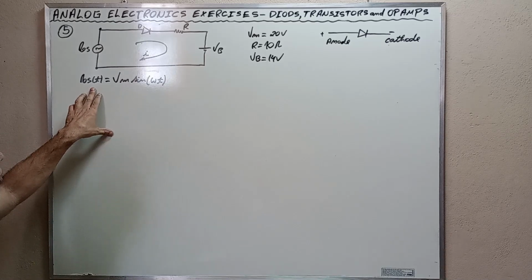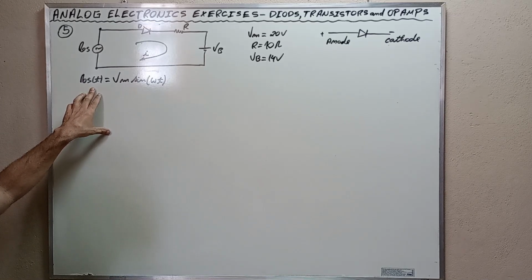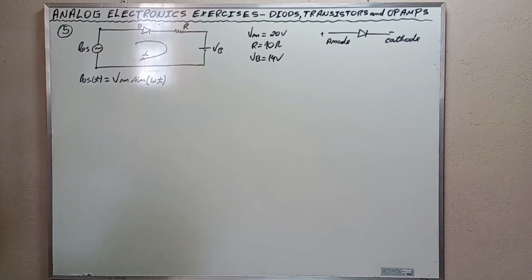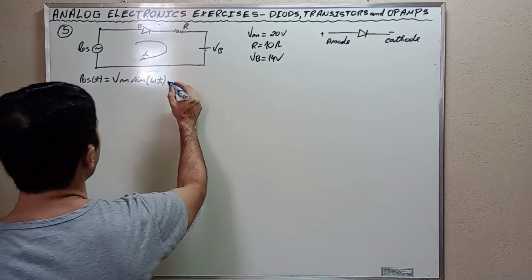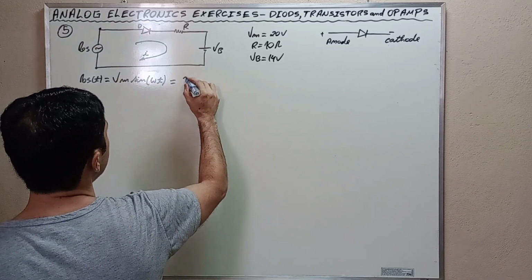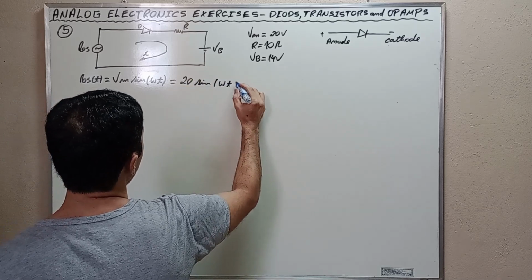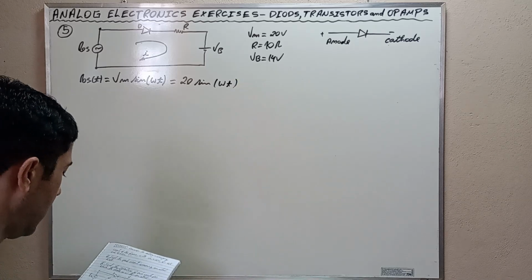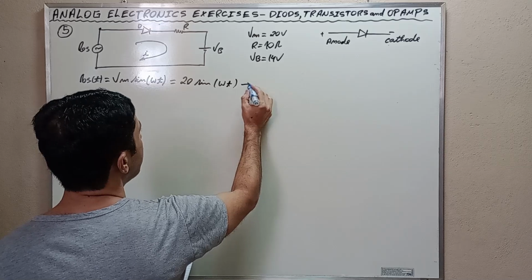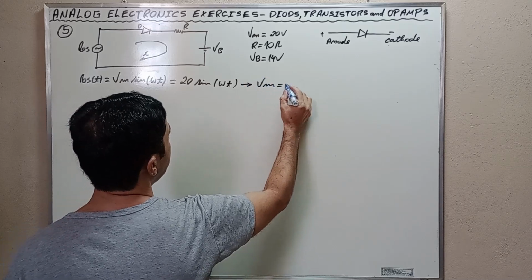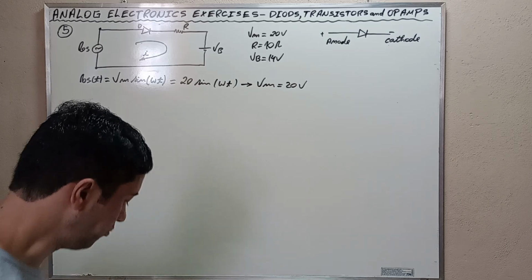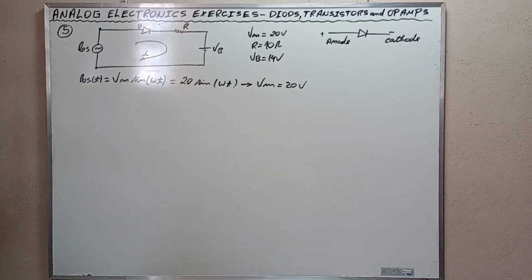And we are going to use this expression of the voltage of the power supply, okay? The peak current occurs when the sine wave source reaches its peak amplitude. Vs is equal to 20 times the sine of Wt, and its peak value, of course, as the exercise said, is 20 volts, okay? Consequently, the voltage across the resistor